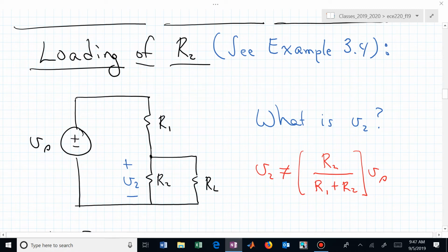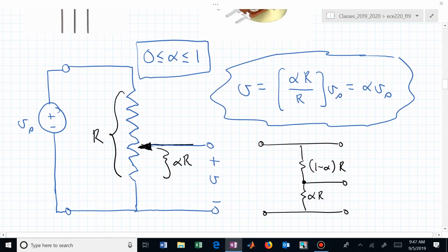Let's get back now to the cautionary tale associated with voltage dividers. Yes? Back to the potentiometer. Wouldn't the total resistance of it be the same? So the total resistance in the potentiometer is the same. That's the R. In the example I said if we had a 1,000 ohm potentiometer, that's 1,000. So that's what we were always putting, the total series resistance we were putting in the denominator. That's the R in the denominator of our formula. Is that what you were asking?